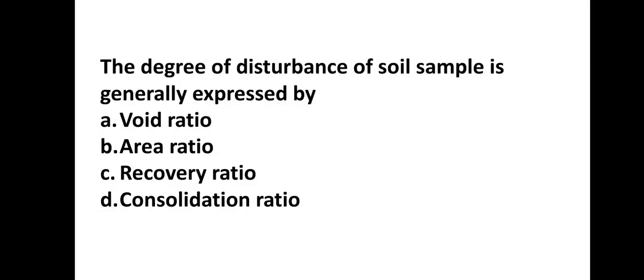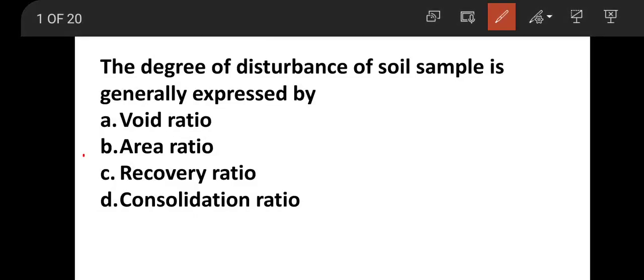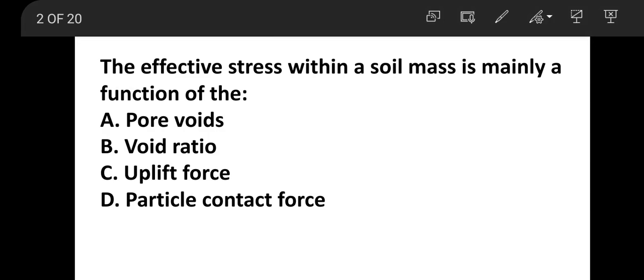So first question, the degree of disturbance of soil sample is generally expressed by. So here the correct answer will be area ratio. Next question, the effective stress within a soil mass is mainly a function of. So here the correct answer is particle contact force.